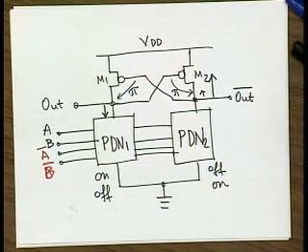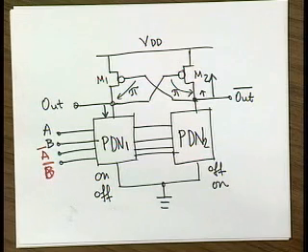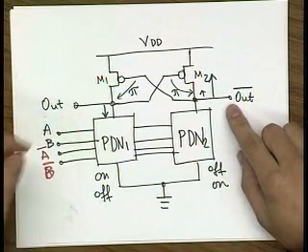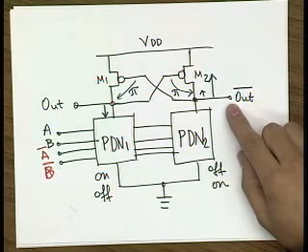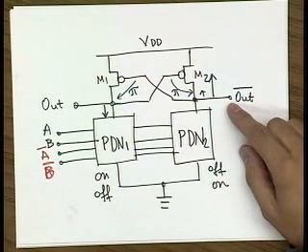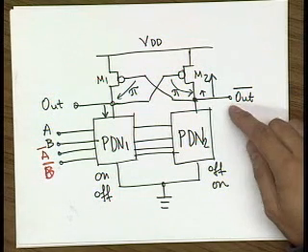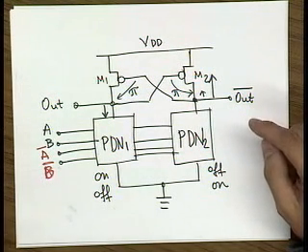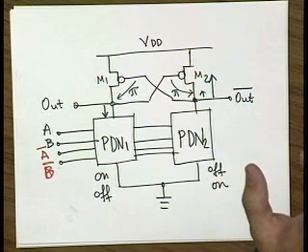So now what you are doing here is basically a couple things. First of all, you are implementing both your true and complementary outputs in one stage at the same time. You remember in static complementary CMOS logic, if you have to implement an AND function, because your complementary CMOS is always implementing an inverting function, you need another inverter stage.